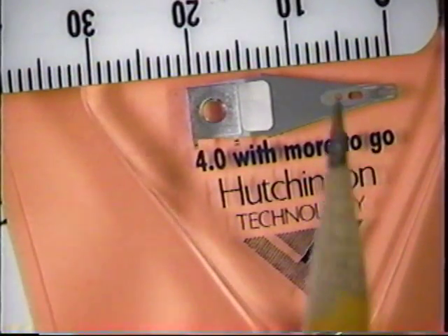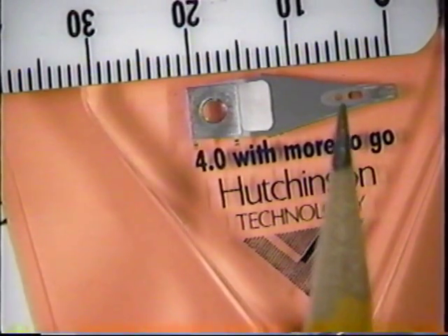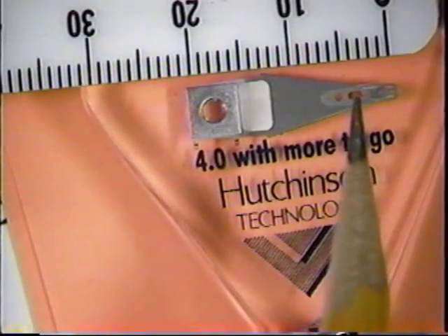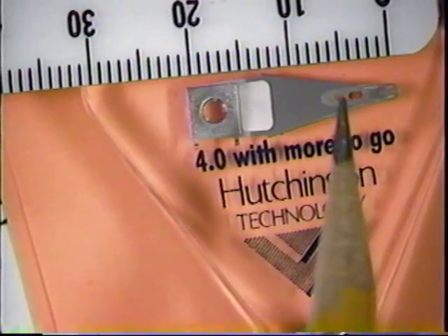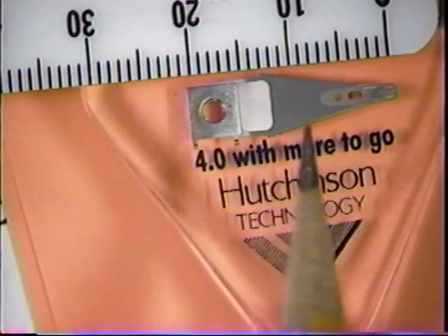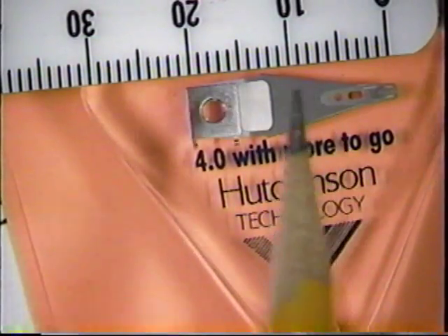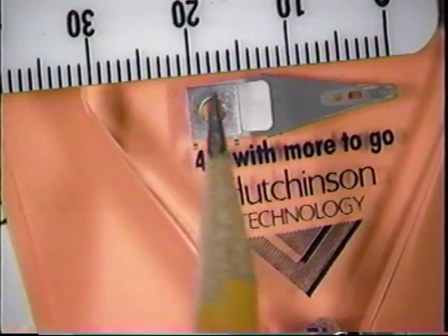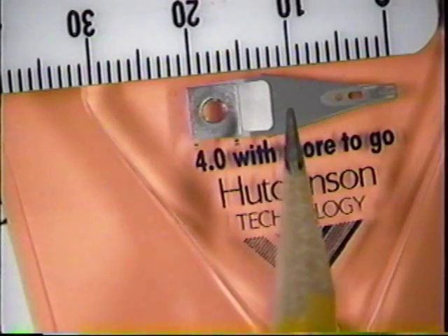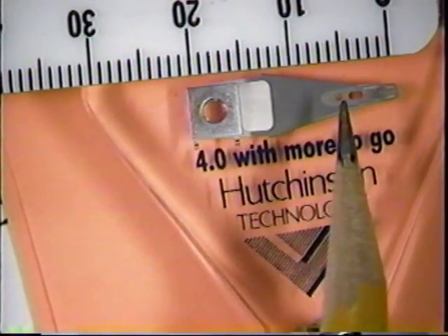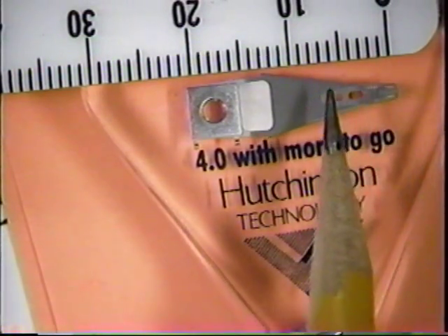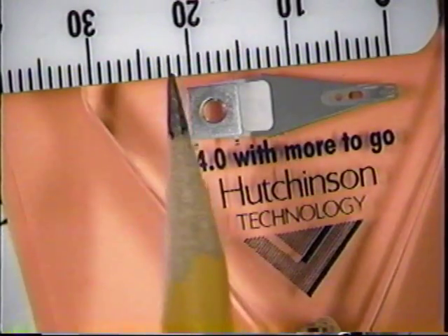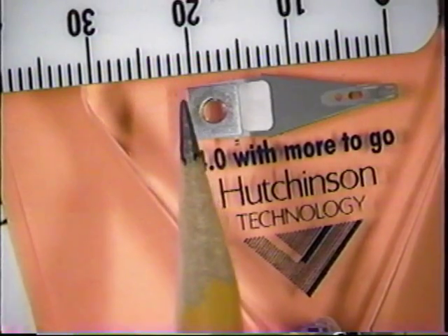There, I think you can see it. A wire actually goes through this particular feature right here, this hole, and wraps through on that little slotted feature. And this is a part here that we use in all of our computers. It's got a stamped stainless steel base. It's got a long flexure beam here, and it's got another piece out here that's laser welded to the flexure beam. And we're looking at a distance of 21 millimeters.